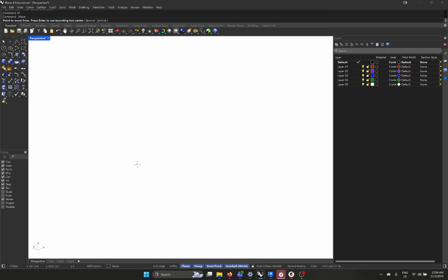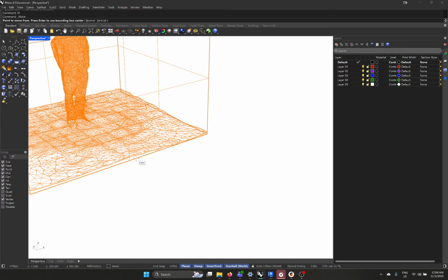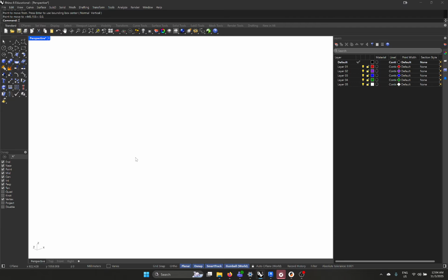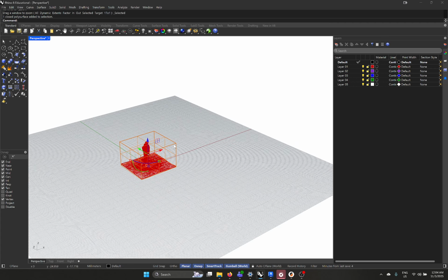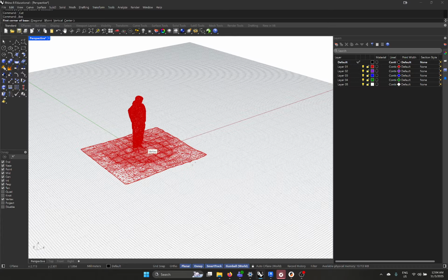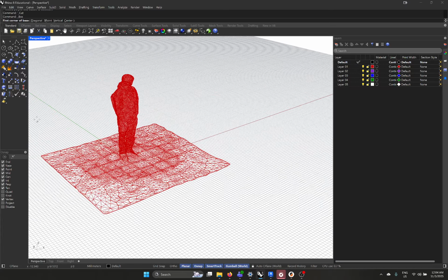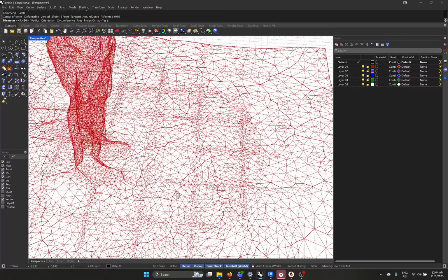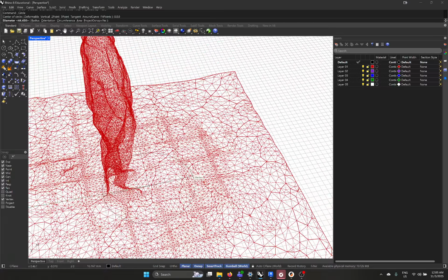And then I'm going to take this, go from the center, bring this to center my file again. And from the center, I'm going to create a cube. Or maybe I'll actually create a circle. So I'm going to type 0, 0, 0. So I'm going to create my circle right from the center of the work surface. I'm going to make this, let's say 10 millimeters in diameter.